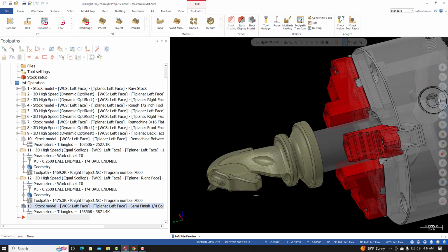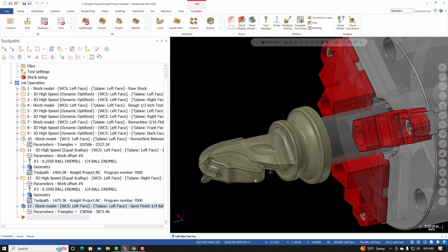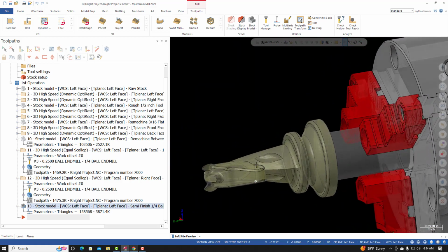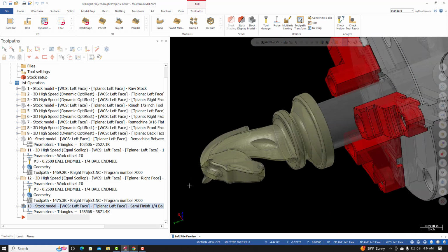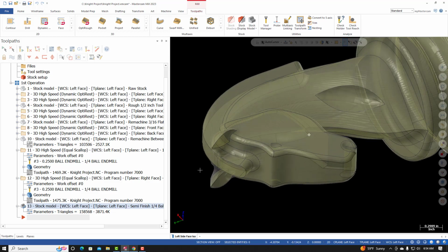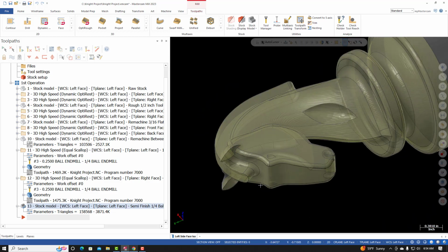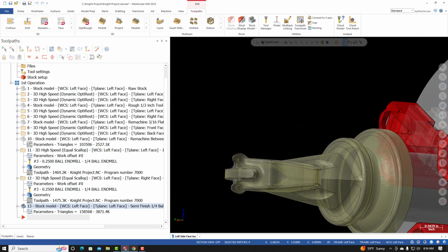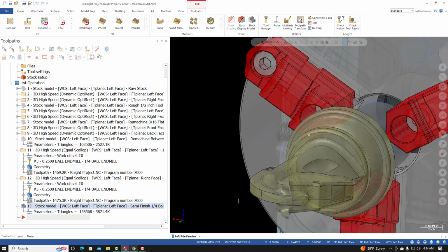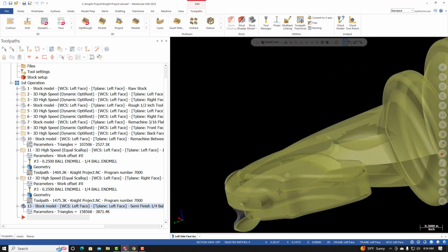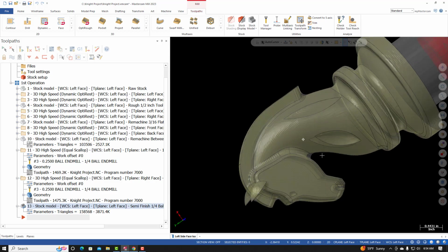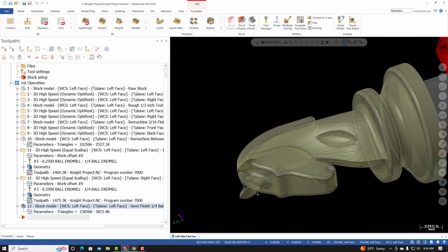So Mastercam just created the stock model, and you can see that it's starting to look like the finished part. Now, there are some areas that we will not be able to get to with the tools that I'm using. If you had some smaller tools and wanted to get between the ears and focus on the areas that the tools we're using can't get to, you could machine it to the exact model.